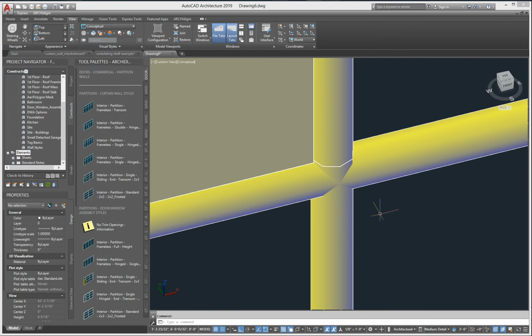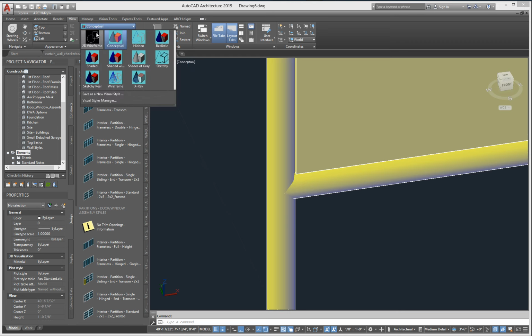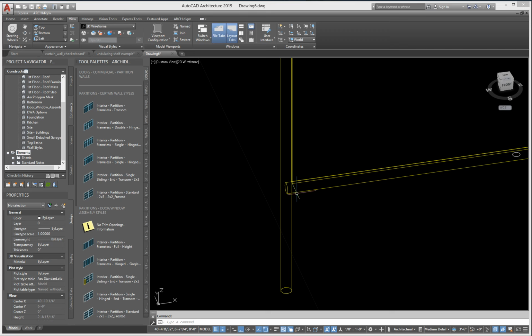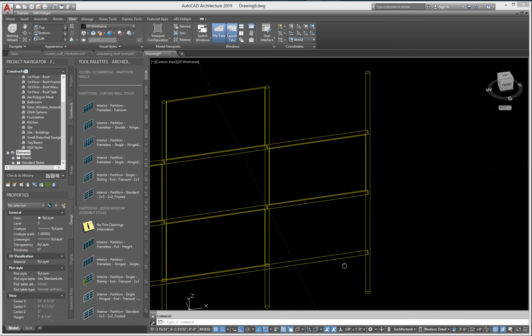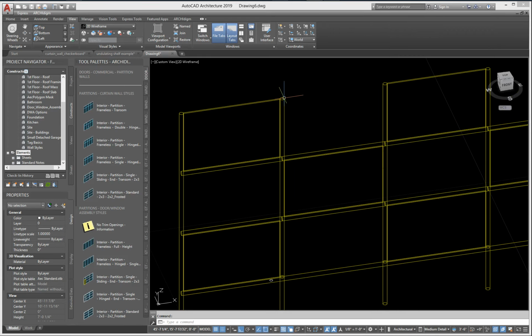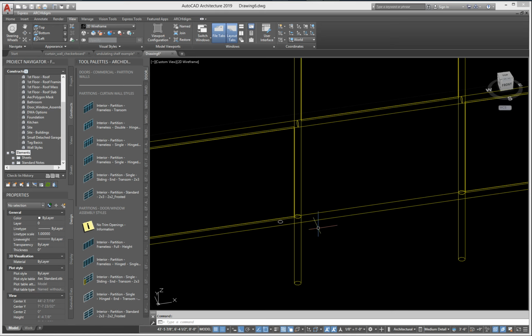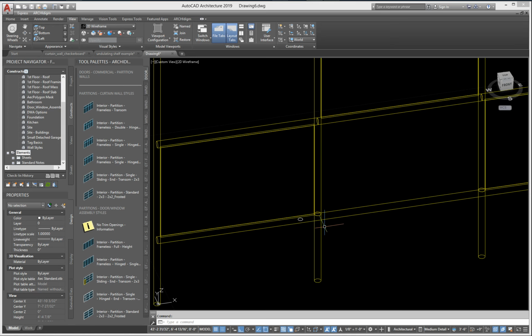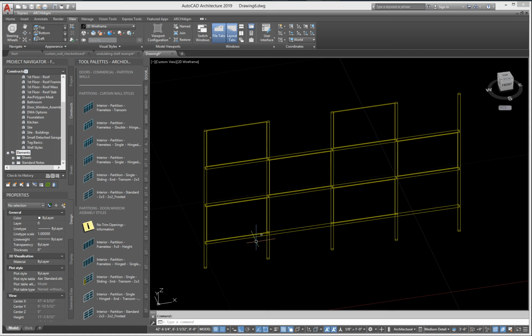So the reason, well, let's start over here. You can see that works, and all I did was protrude the horizontals all into the end pipes on both sides, right? So that works good. And then I didn't want to do the verticals because I don't want the verticals to get any taller or shorter. So I just made the legs shoot all the way up into that bottom horizontal, right? And when you render this or you do a projected elevation, you shouldn't see any of this stuff. It'll just hide that stuff.